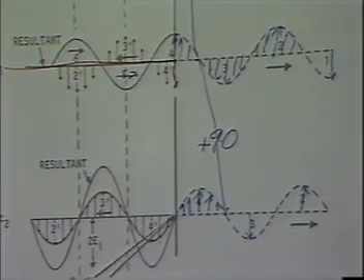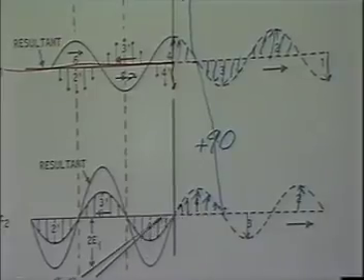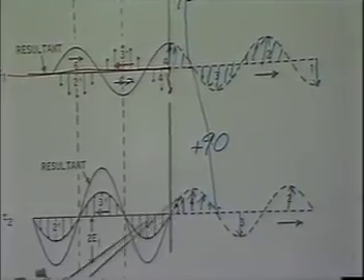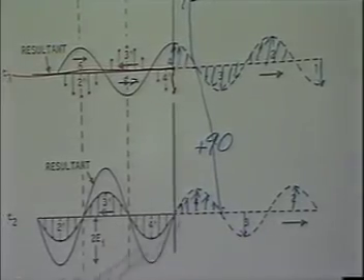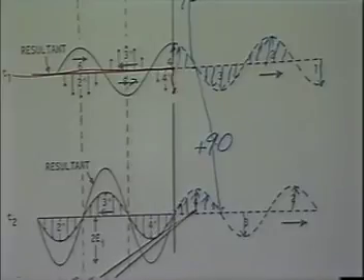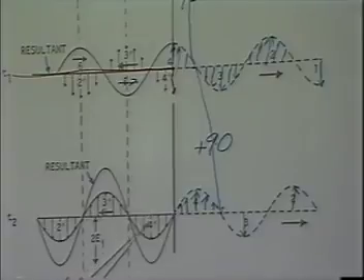The next one, instead of going over here 60 degrees, it went over here 60 degrees. It's negative instead of positive. The same thing happened. Instead of going to the right 90 degrees past the interface, it hit the interface and went back this direction, and it's negative instead of positive here, again because it reflects 180 degrees out of phase at a short circuit.